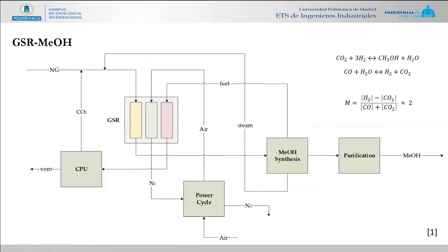Okay, so let's go on to describe a little bit how this gas switching reactor cluster is integrated in the methanol synthesis concept. For methanol, we have these reactions taking place in the synthesis loop, the proper methanol synthesis and the reverse water gas shift. And we must introduce a syngas stream with the following module, right, because of the stoichiometric requirements.